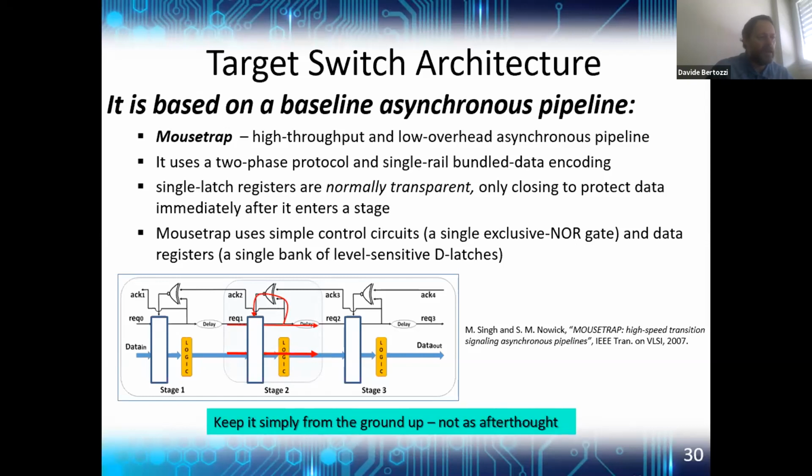This request signal is also sent as the backward propagating acknowledgement signal, which allows the previous stage to send different data. When this stage under test is getting the acknowledgement, this acknowledgement signal will make the latch transparent again, and we are ready to store the next incoming data.